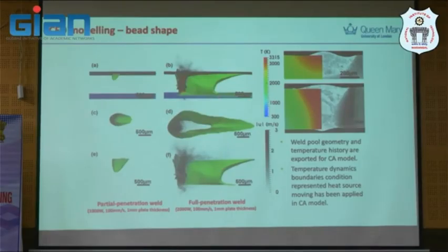There may be some instability in the keyhole and it can trap the porosity behind the bead or in the structure, which is not preferable. What we're trying to do is understand how we can go just before the full penetration, but heat enough of the material beneath the surface. In this case, we try to